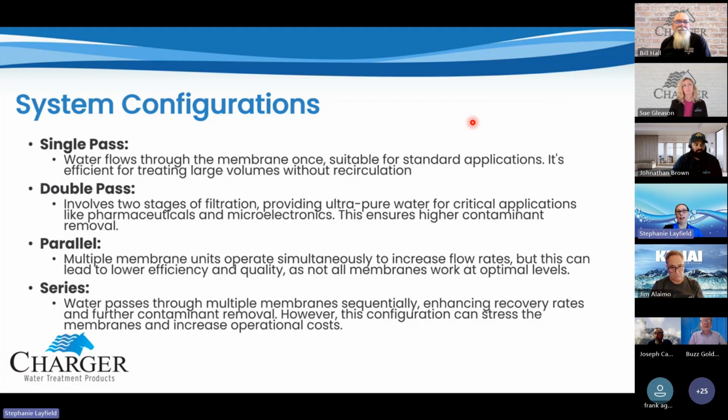And fortunately, it's not going to be a complete failure with scale buildup on there. It's just going to be an increase in your pressure having to go in and decrease permeate coming through. So it's just slowly going to scale up from the backside forward.